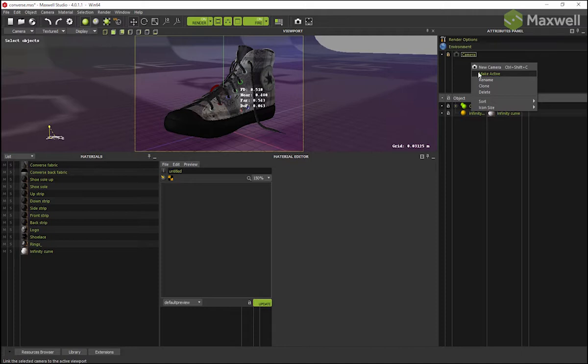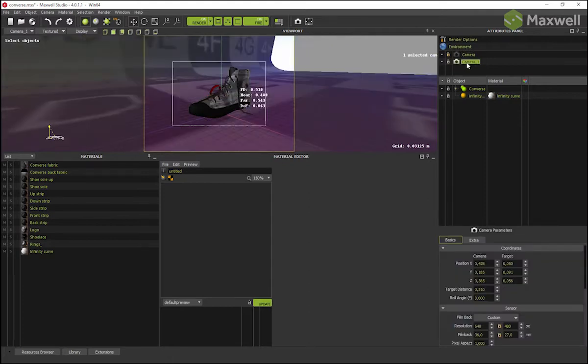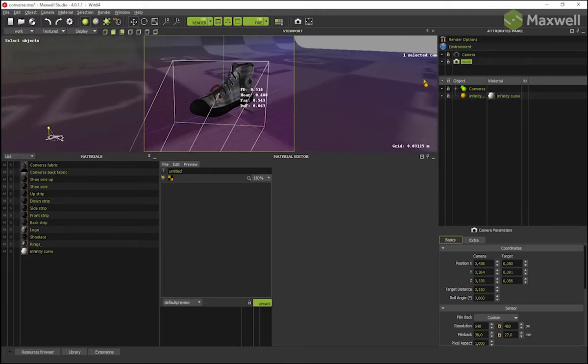Before adding the displacement map to some textures, I'm going to configure the lighting set. To do it, I'm going to add planes to the scene, and I'll put an emitter on them to provide light. Emitters in Maxwell Render are part of the material system. An emitter material must be applied to the geometry you want to emit light from.